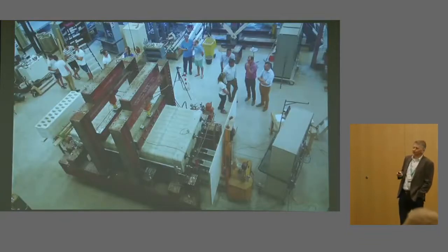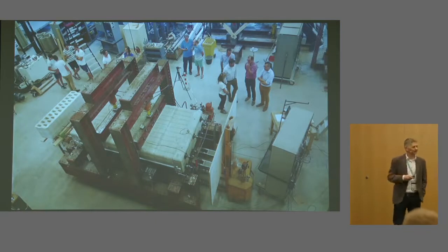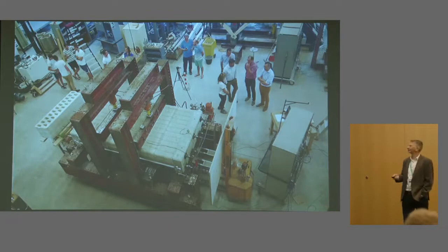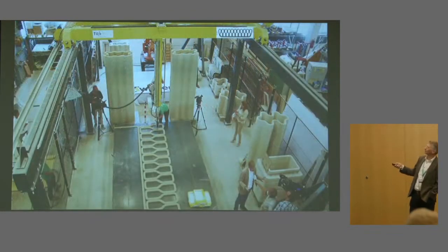Now, then we started to do material tests. The next step was we did some tests on scale elements. This is not a real size. But on a scale element in the lab by pre-stressing, see how it behaved. And we expected it to behave like just a normal pre-stressed concrete bridge. And it does. This is just concrete bridge. You don't need new codes. This is just concrete that is pre-stressed. You need new codes to determine the material properties because they don't fit. You can't pour them in a mold or a cylinder to test them in compression. That's not possible. But this behaves like a normal bridge. It's just concrete at the end. Okay, when we knew that it worked, we started to print the real one, 3.5 meter span, so it's approximately a meter of height.